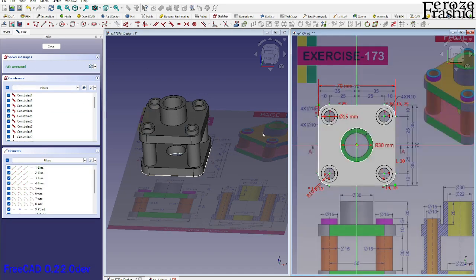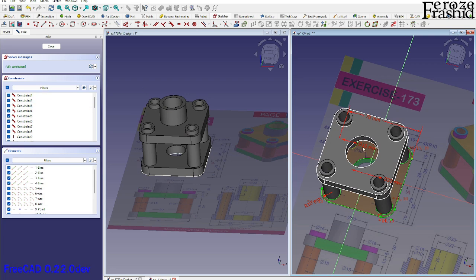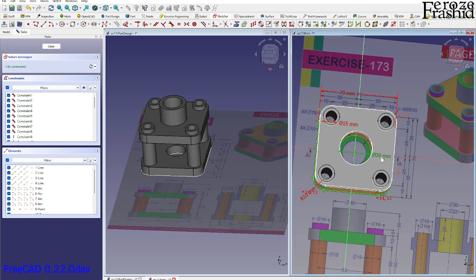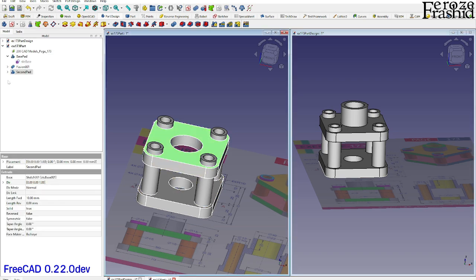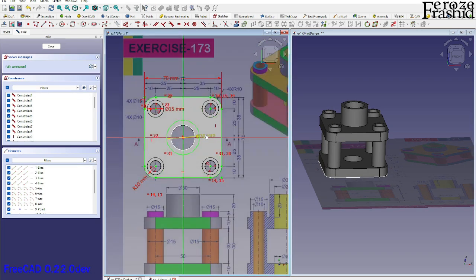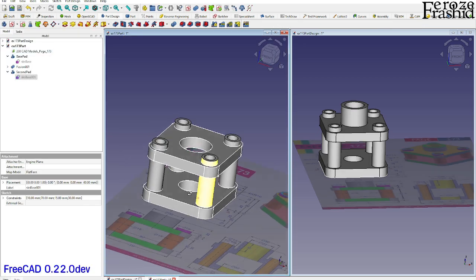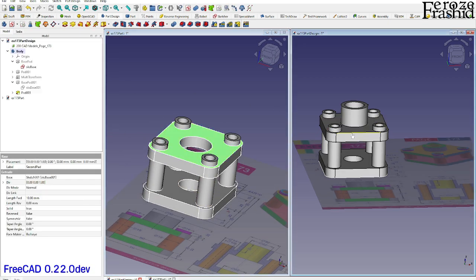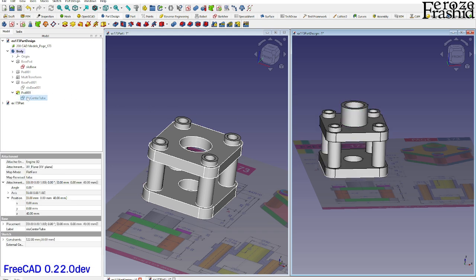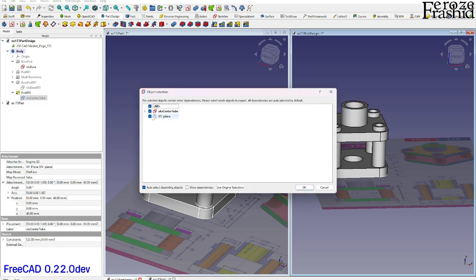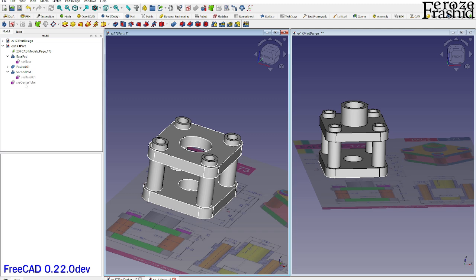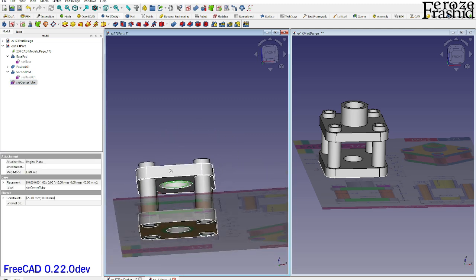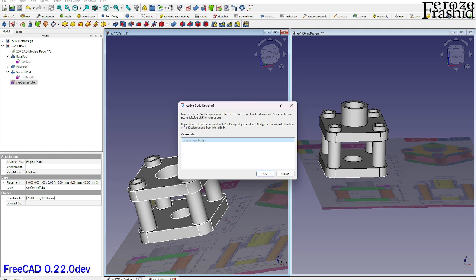So come here to the base pad, make this 30 as 22. Cool. And because we copied this one with its own sketch, that is still showing 30, which is fine with me. And what I want to do is take this sketch from here, copy only the sketch, and come to the part one and paste it over. I think it's at the same location now, and then extrude that for 30.